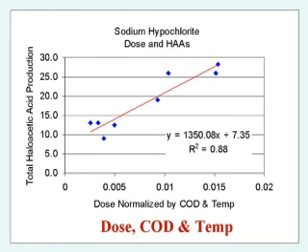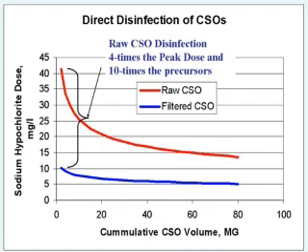As Carol mentioned a little while ago, one of the things you do is check your chlorine levels, and the strength of the chlorine has to be entered into this algorithm or your computer. It says, okay, our strength is less, so the algorithm takes care of the increased dose you might need as the potency of the chemical subsides. And that is used in Columbus, and it's producing effluents typically below 100 colonies per 100 ml at all times during that CSO process.